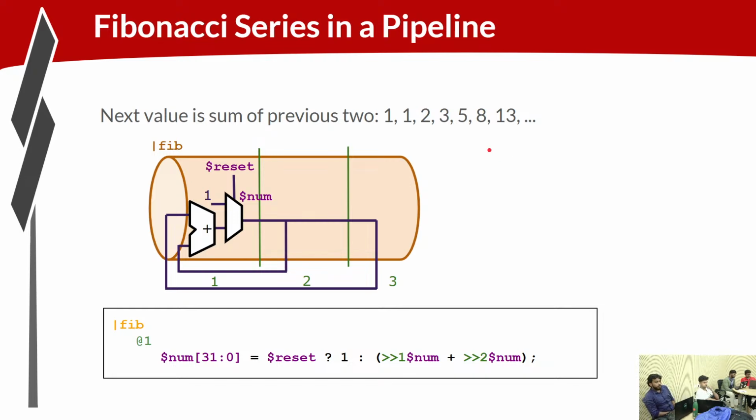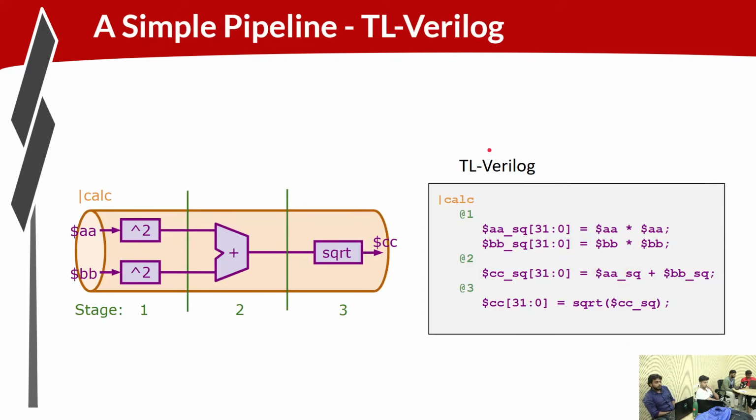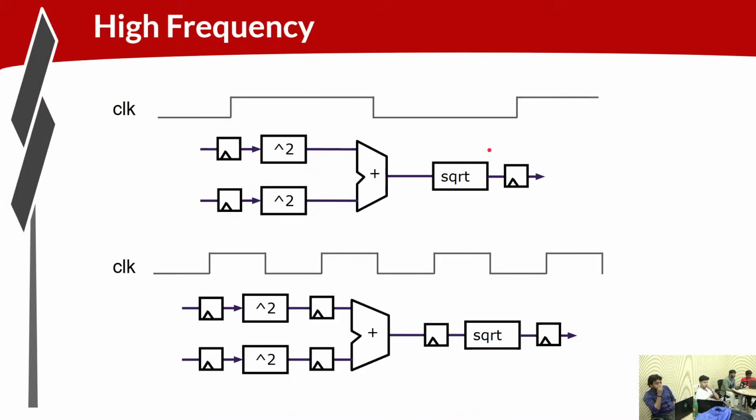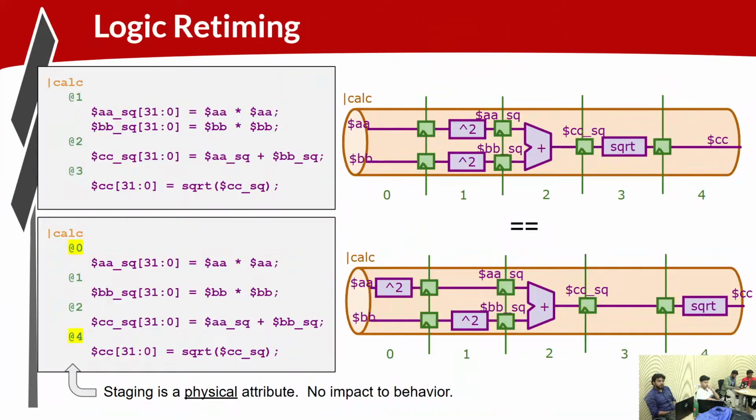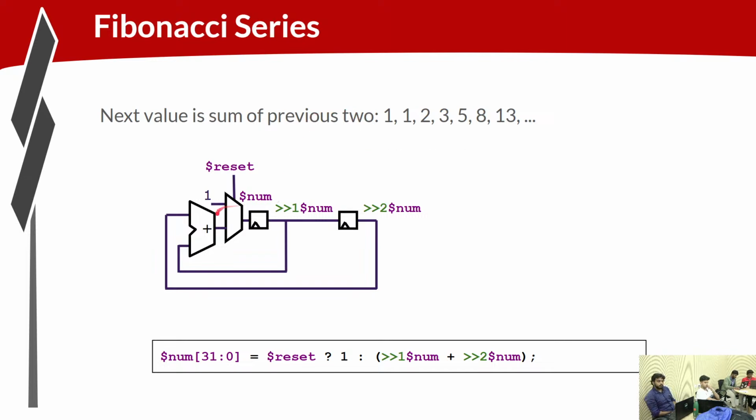I think that's what we did earlier with Pythagoras' theorem. We started with a one-stage implementation, and then we stretched it out over multiple stages. So that's the point: once you give yourself the context explicitly of a pipeline, you can very easily take this mux and push it through a flip-flop, retime it, and know that you haven't broken the functionality.